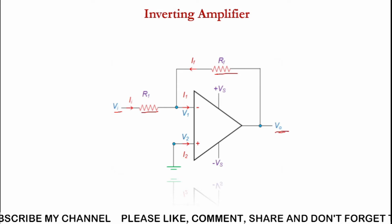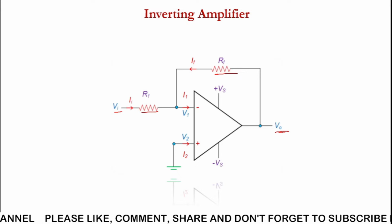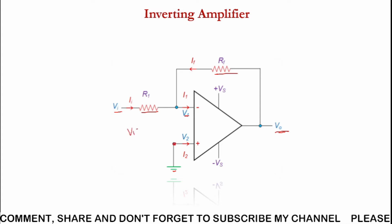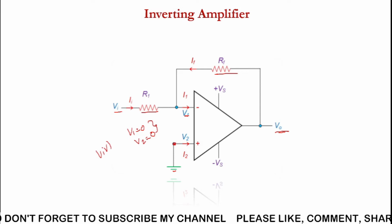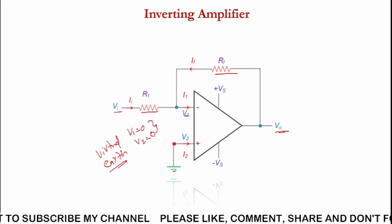Look here, Vi is the input, and the resistance R1 and resistance RF are there, RF in feedback, while R1 is at the input terminal. So this is the way the inverting amplifier is. According to the virtual earth concept, V1 and V2 are both at the same potential, so we can say it is equal to 0.